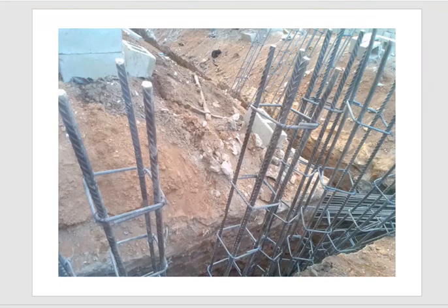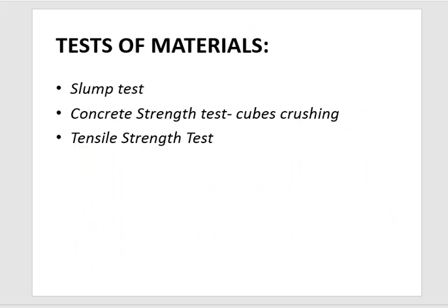This is the first material I tested. These are my reinforcements, and this is what we did. We did a tensile strength test. Okay, we can do a slump test, we can do a concrete strength test, that's cube crushing, we can do a tensile strength test for our reinforcement. So I did the tensile strength test of the reinforcement.